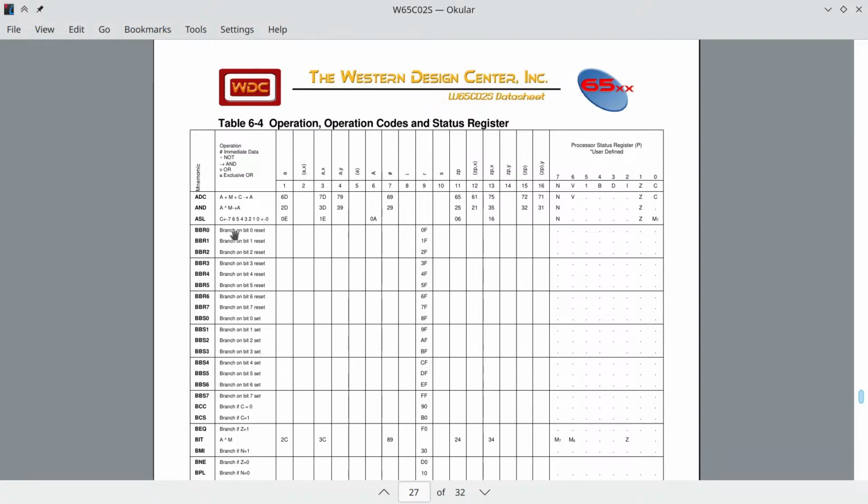We're saying the bits 0 through 7 of the operand, of whatever it is we're working on, need to be shifted. So 0 goes into bit 0, 0 goes into bit 1, 1 goes into bit 2. That's the arithmetic shift left. And then bit 7 goes into the carry.